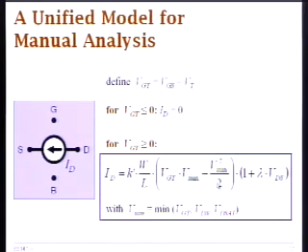That's given in this unified formula where you have K prime W over L, VGT times Vmin, and you also include channel length modulation, with Vmin identified as the minimum of VGS minus VT, VDS, and VDSat. If Vmin is VDSat, you have velocity saturation. If Vmin is equal to VGT, you have the conventional saturation equation, and if Vmin is equal to VDS, you have linear mode of operation, and everything falls into place quite nicely.